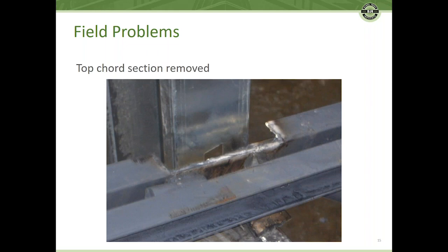In this particular case, the guy that was putting in the stud wall, I guess, felt like it was more important to get the stud where it was than to not modify the joist, and so obviously that's something that's going to need to be evaluated and modified to get the material that was lost in the top chord replaced.